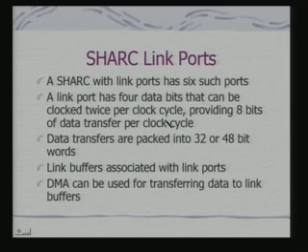A link port has 4 data bits that can be clocked twice per cycle. So, effectively what you are providing is 8 bits of data transfer per clock cycle. And these data transfers are packed into 32 or 48 bit words. Each link port is associated with link buffers. These link buffers contain the data which is to be transmitted, and you can use DMA to transfer the data to and from the link buffers.